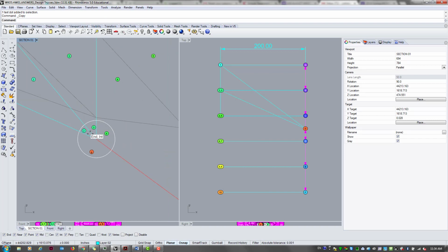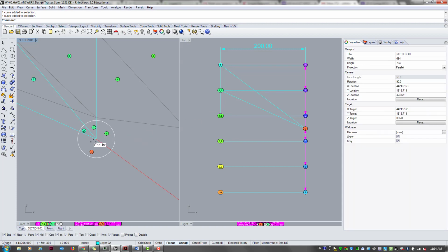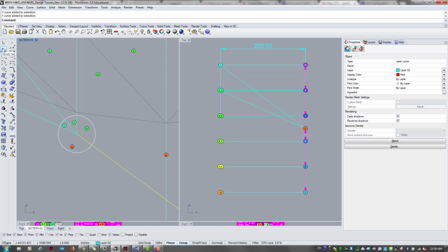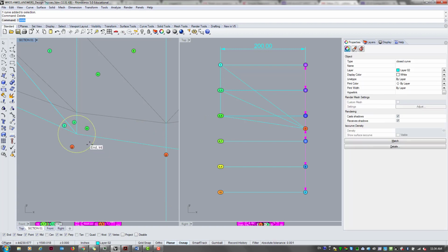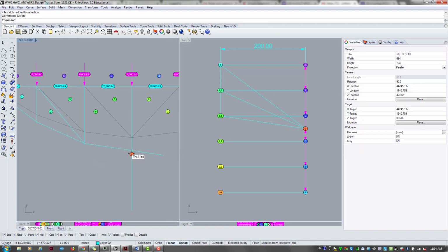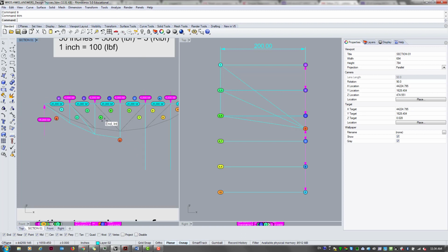So really we already know 2, 3 is 0, 3, 4 is vertical, we already mapped it. G2 we already mapped that, so the only thing we don't know here is 4G, which should be determined by the line that connects point 4 and point G on the force diagram. So the bottom chord here should take the same angle as the force diagram, therefore that red assumption is wrong. And I'm going to trim that vertical there, and that diagonal chord should also connect from corner to corner.